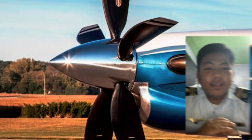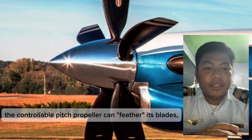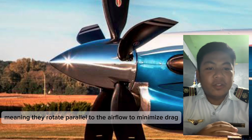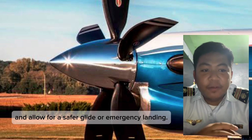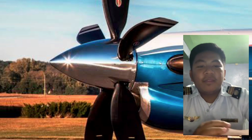Feathering. In the event of engine failure, the controllable pitch propeller can feather its blades, meaning they rotate parallel to the airflow to minimize drag and allow for a safer glide or emergency landing.